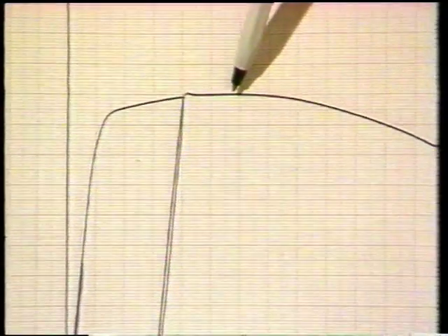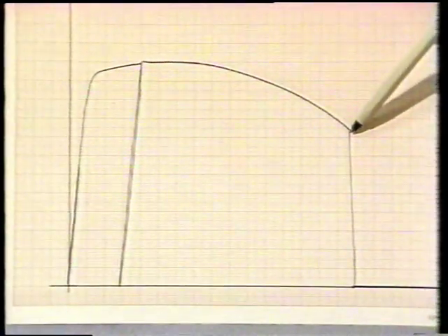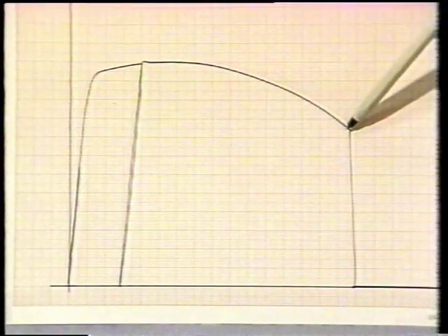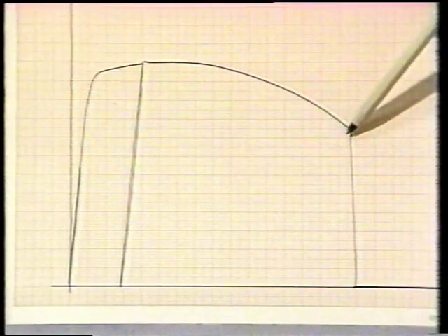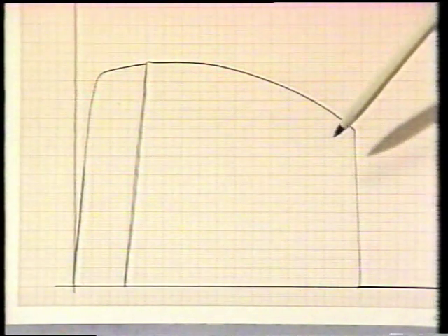Now, if we want to, we could also measure the breaking load and divide that by the area of the fracture, and that would give us the fracture stress. Although normally, that's not recorded when we're expressing strength properties. It's a useful thing to know.